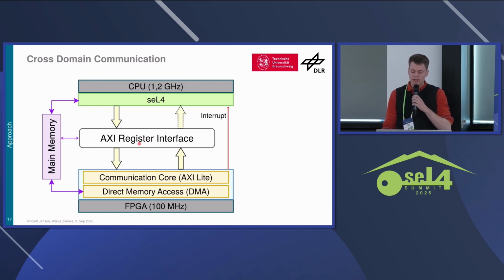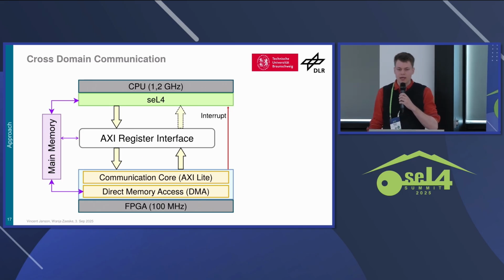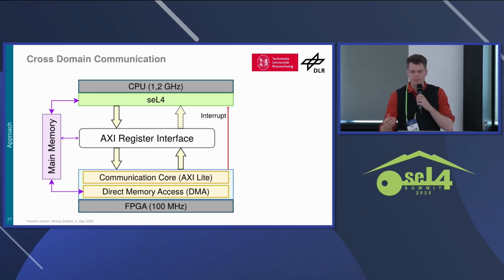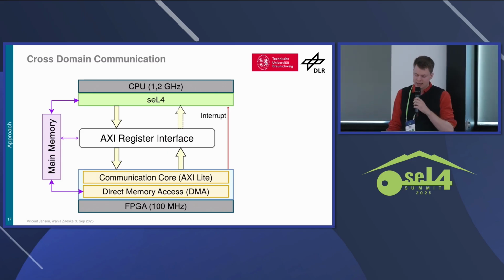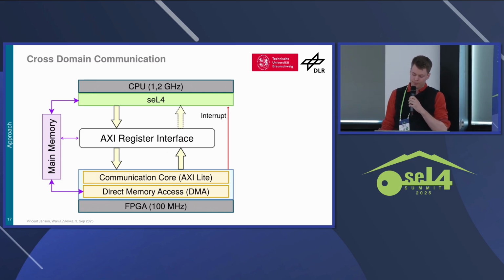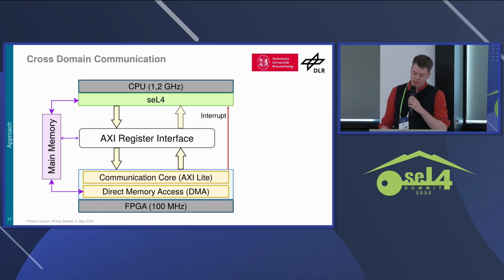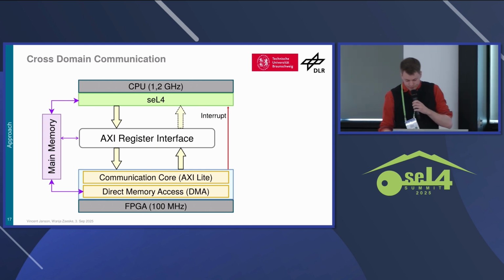And we also have a set of memory mapped registers using an AXI register interface that allows us to have a small amount of data that is directly accessible both to the programmable logic and to the programmable software. Now, these both things, the AXI interface and the DMA, are integrated on the FPGA, while the SEL4 kernel is our baseline for the software side.